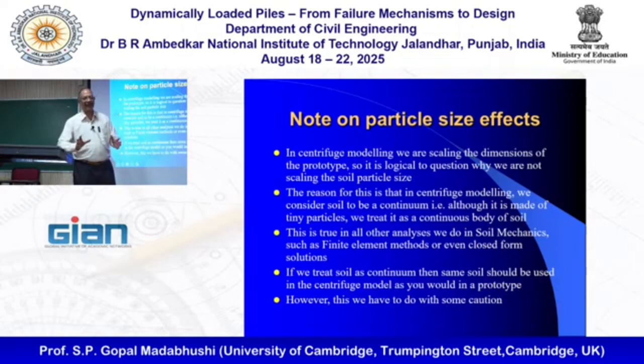Somehow a pile needs to be a bit bigger. And you're quite right in thinking that, because if I have a needle, the number of particles in contact with the needle will be maybe 2 or 3 soil particles, whereas a real 500 millimeter diameter pile will have thousands of particles in contact around it. Now, both are not the same because I can move individual grains easily. So this thin pile won't do the same as the large pile, although you got the right stress. That's because we made the G so high, we are starting to violate the principles of continuum mechanics.